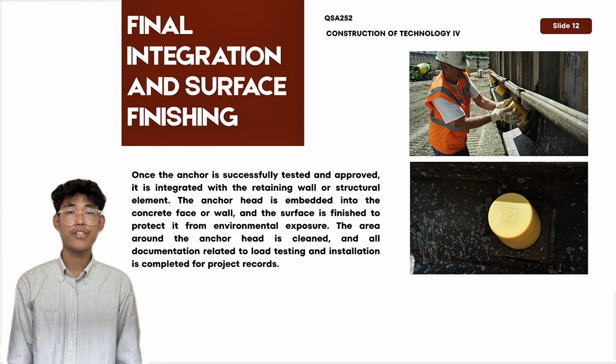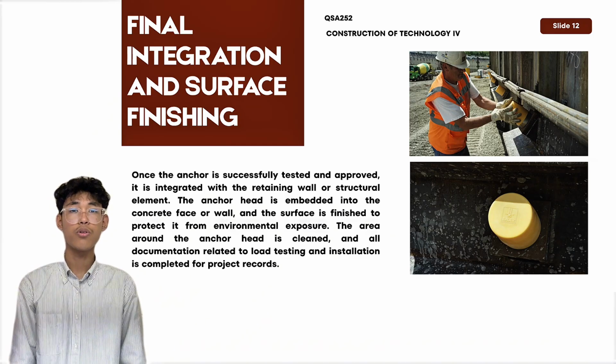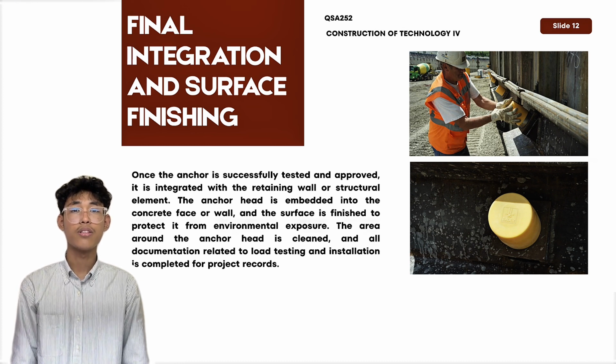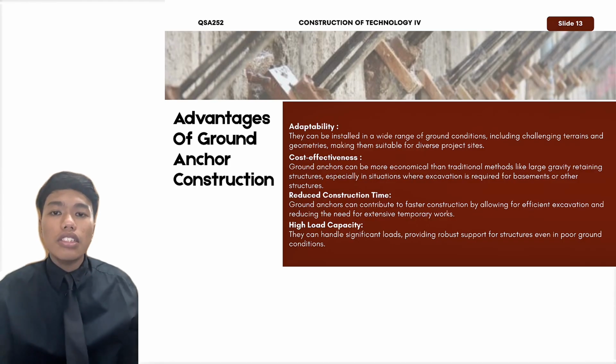Finally, we have integration and surface finishing. Once an anchor passes the test, it is integrated into the structure, usually embedded into a concrete wall or face. Then, the area is cleaned and protected against environmental exposure. The surface is finished properly to give it a professional and safe appearance. All the important documents, such as testing results and installation records, are completed and stored as part of the project documentation.